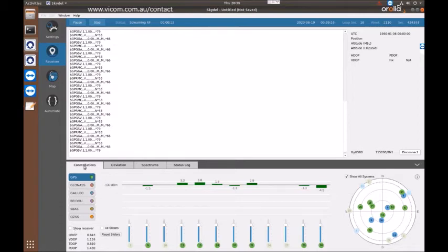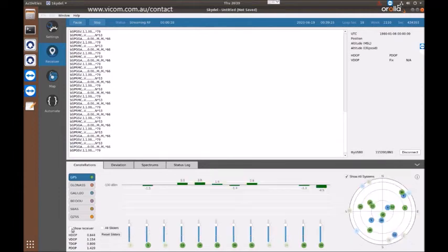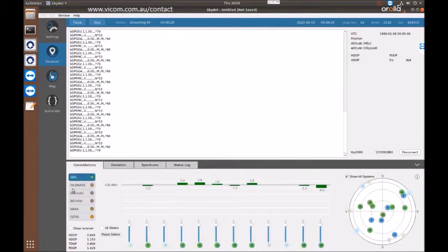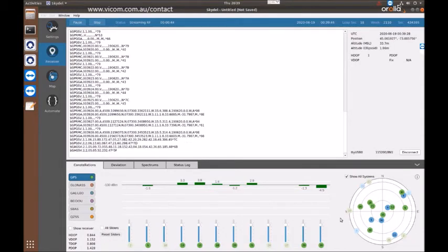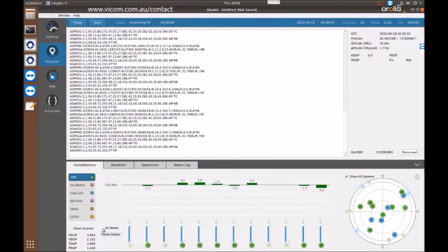When I look down at the bottom at the Constellations tab, when we're running, this is where I can view the satellites that we're generating. Here, I can view them independently of each other or all in the same sky plot. When I choose these, I can see which signals we're generating and what their relative power levels to each other are. And I can adjust that using these slider bars as well. So for each individual satellite, I can make some changes. For the entire set of satellites, I can make some relative changes as well. So I can do individual or all.